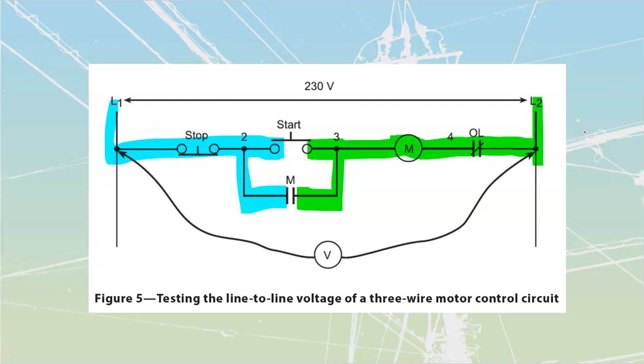Most common thing that it's going to be inside of your motor, if the motor's not starting, by the way, before I even pull out my meter, I'm going to just press the overload reset because usually it's just been a momentary overload that's happened and that's been what's kicked the entire thing out.